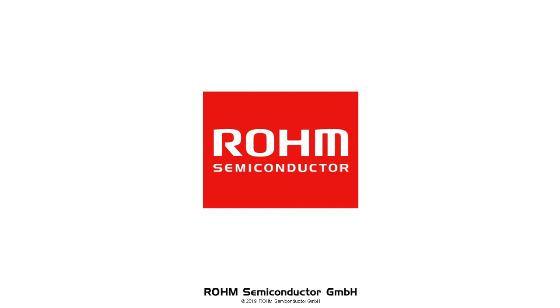Here is, so far as I can see, the last question. In the datasheet, it says that the buck 7 requests 22 microfarad, whereas all the other bucks will need twice 22 microfarad. Why is that? Yeah, I said it during my presentation shortly. The buck 7 has an output capability of just 1.5 amp, means it's half of all the other bucks, and therefore it's only requested having there 1 time 22 microfarad capacitance at the output, and the buck remains stable there.